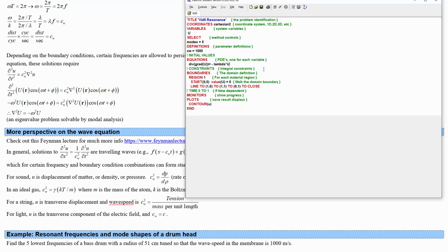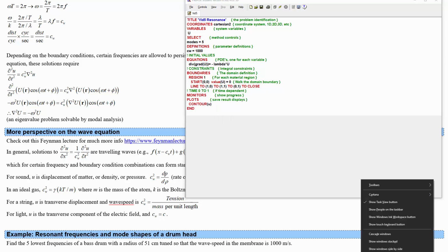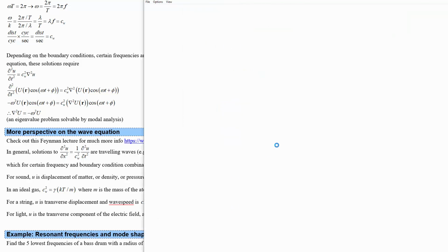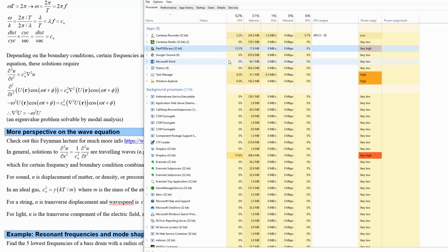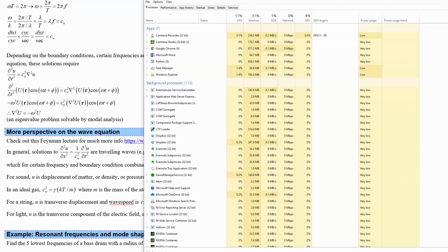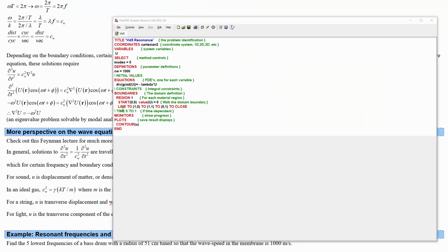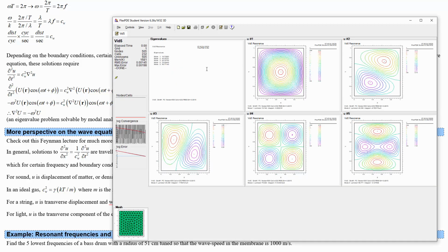So, by the way, maybe this is a good example actually. When this happens, you get these floating point overflows, and it can't actually terminate. So what you have to do is open up Task Manager and then go down to Flex PDE 6 and hit delete, cancel that. And after a quick video edit, you'll be right back to where you were. So we are ready now with value is equal to 0 to run it, and things worked.